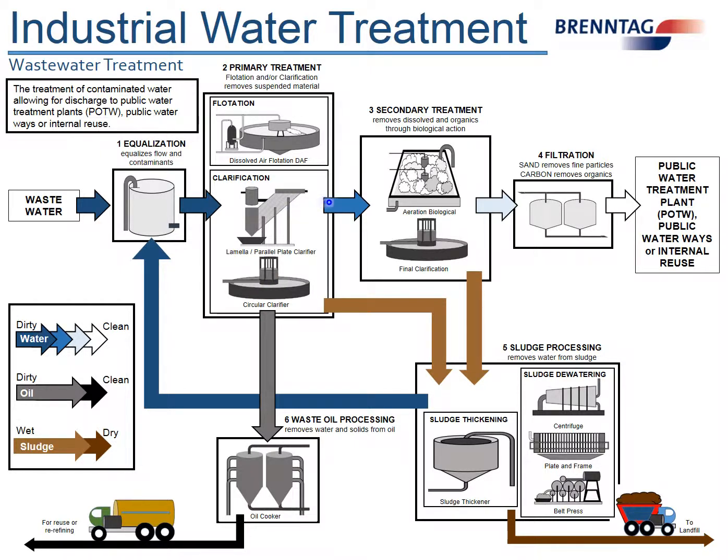The water then could pass into what's called a secondary treatment, and that consists of a biological treatment plant. In this case, we're showing an aeration pond where air is introduced to the water, where bugs, as we call them, will start to break the organics down in the wastewater. This water will then be allowed to settle out. The bugs will settle to the bottom and then be brought to sludge dewatering.